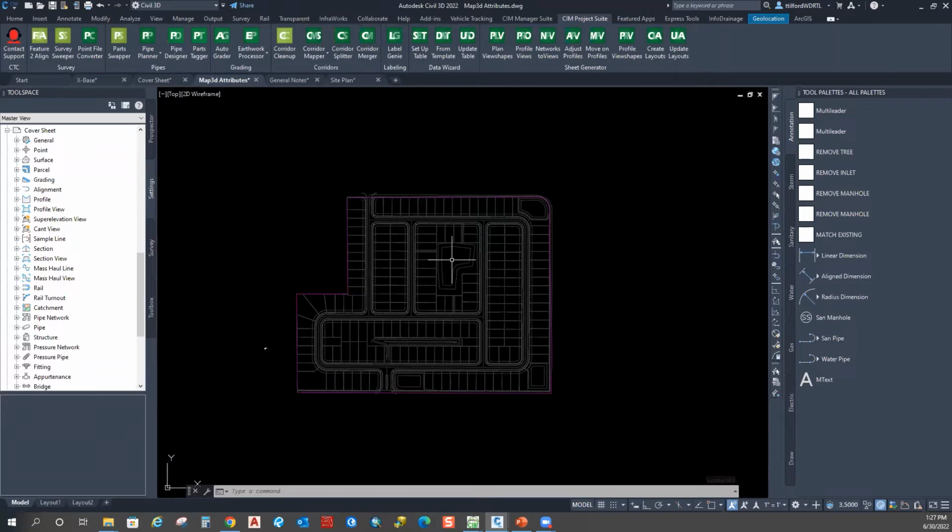And GIS data usually has object data attached to it when you bring it in. So how can I animate some of that or annotate some of that when it comes in? That is basically using attribute data. You can create attribute data using attribute definition templates. You can also create it within the block using map annotext. And then as that block comes in, it will put that data in. Let's go ahead and look at some of those workflows.